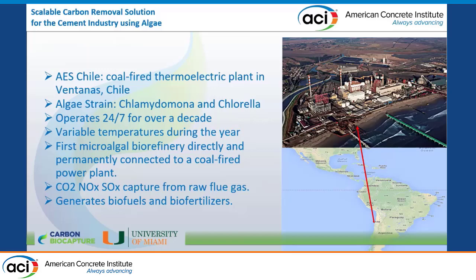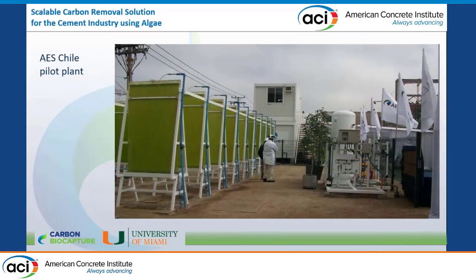And this is not theory, even though the videos I've shown so far appear to be. There have been 2 plants, the first one in Chile from a coal-fired thermoelectric plant in Ventanas that has been working for 10 years, actually 12. So over a decade working nonstop permanently, capturing at higher than 80% efficiency. This is how the plant looks, about 35 total panels. And you can see the panels are in real size. The input of the blue lines, those are the water that is used as it evaporates or whatnot. And in the bottom of the panels, you feed the flue gases.